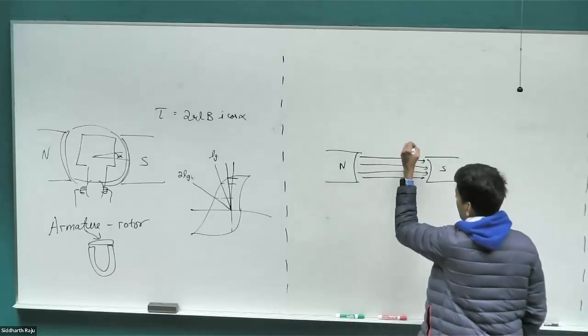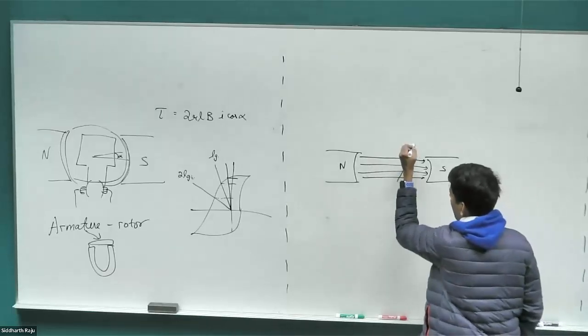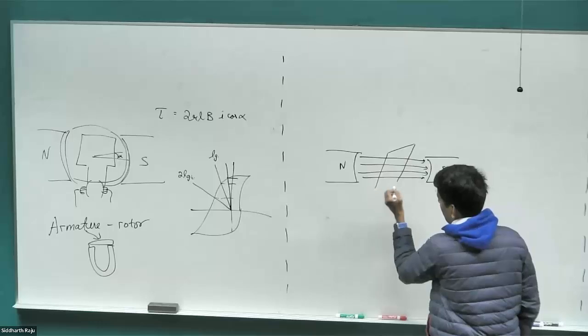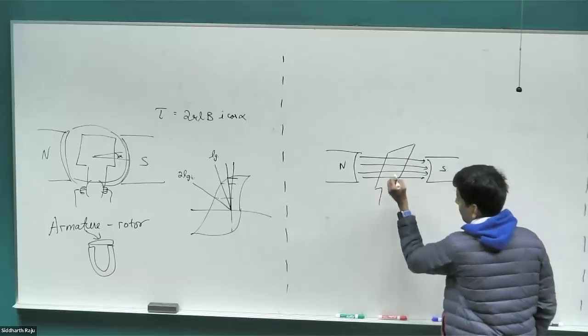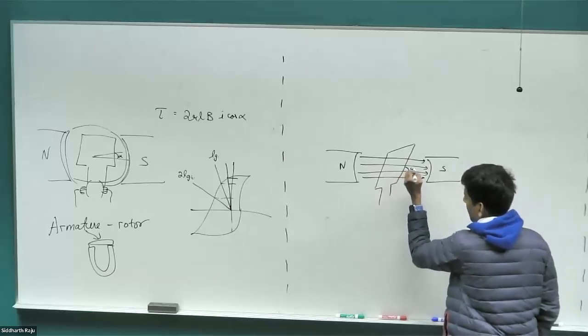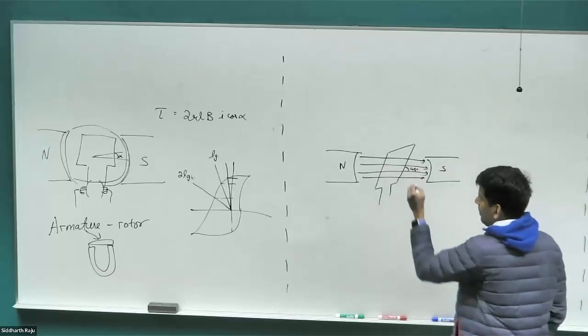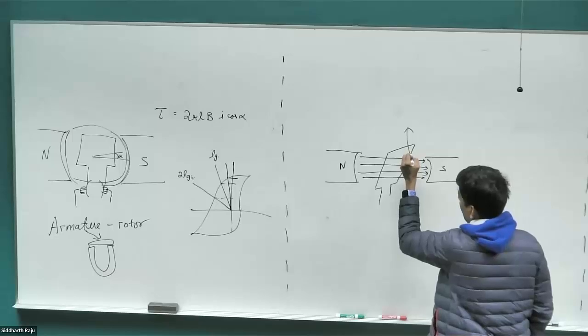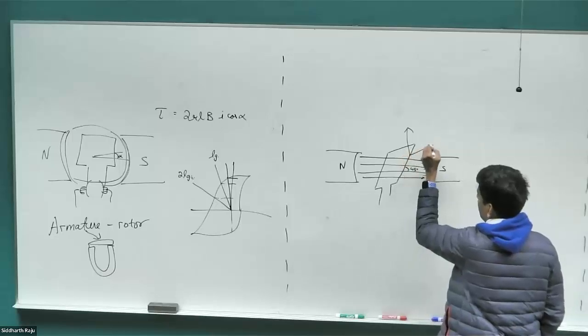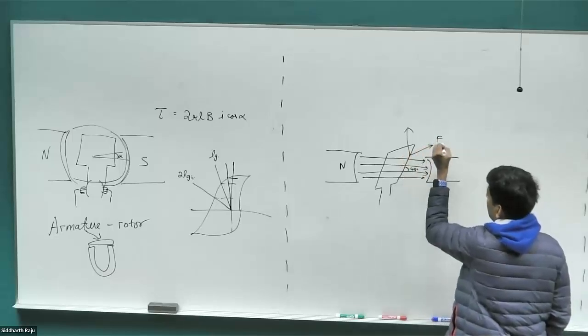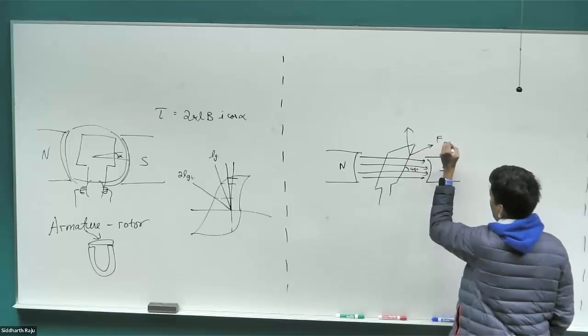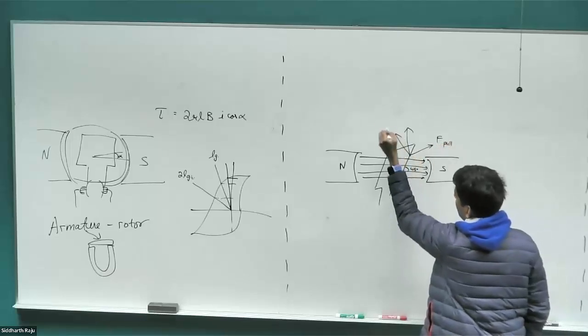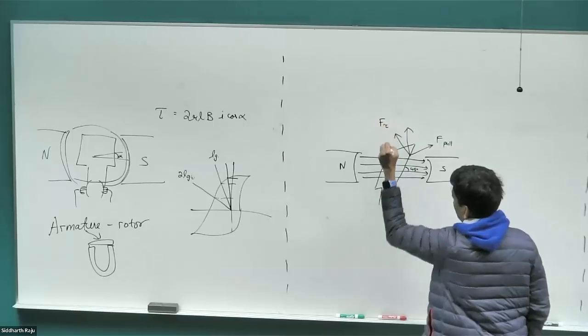And then when our winding was at some odd angle, say 45 degrees with respect to the field line, we computed what this force is going to be. That's how we got the torque expression. Only a component of this force is going towards torque. There is a component of force that is just pulling the wire outwards, and there is a component of force that's producing the torque.